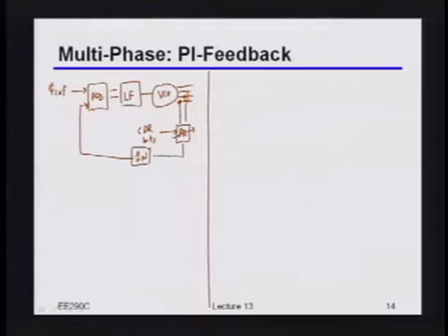Okay? Now, it also has the limitation, or the caveat, that these CDR updates experience the PLL feedback transfer function. But again, since you typically want a low CDR bandwidth anyways, that's not too big of a deal. Okay? So this particular idea, I believe, was first published by some people from IBM in Zurich. That's Thomas Toifl, and I believe this was in ISSCC 2005. So fairly shortly after the previous work that I mentioned.